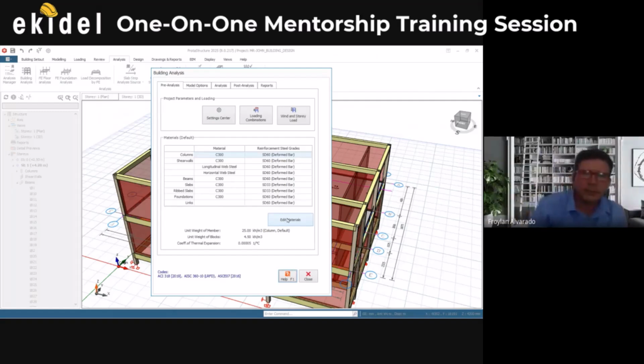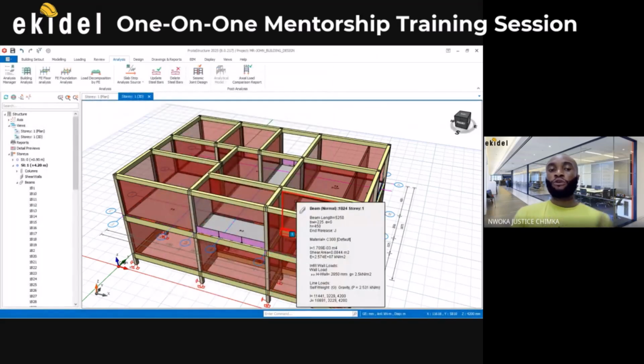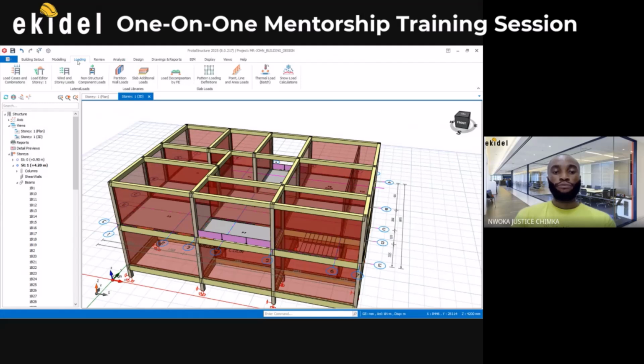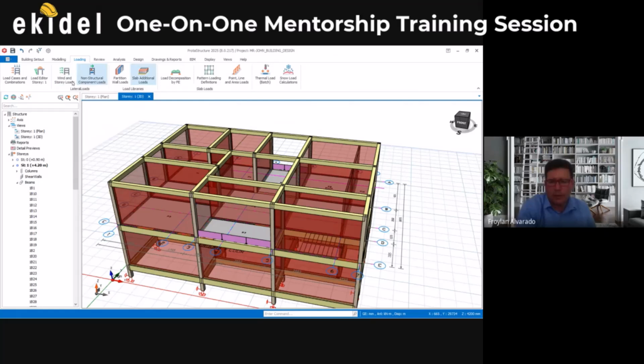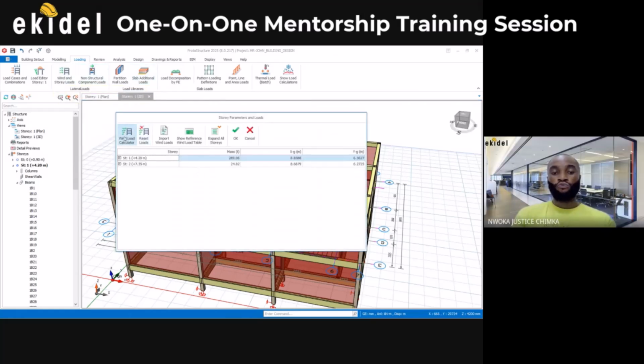Yes. Okay, that's fine. So right now, you know, the thing we did before was just to choose the wind load combination that we added, but we have not actually added the wind speed and all that to this structure. So to now add your wind speed to the structure, it is found under loading here, loading tab. You'll be able to see your wind and story load here. So I'll click on this place now that says wind and story load. Then click on wind load calculator here that you have here.